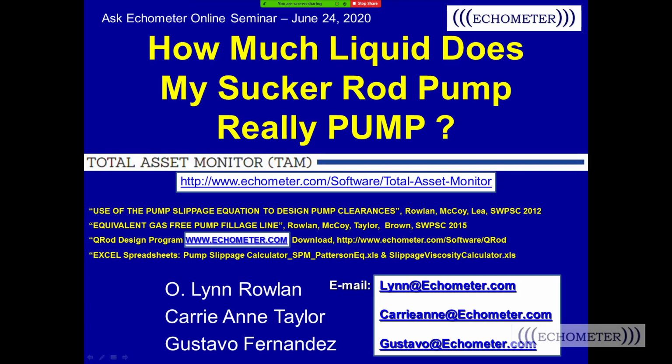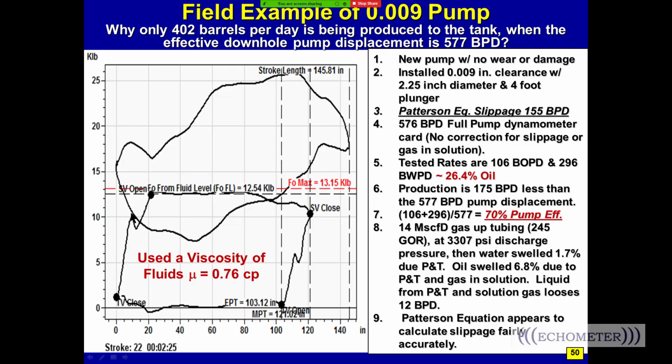Okay, so now you can jump into the last question from Bert. That's yes, slide number 50. You're asking about this little bounce right there and this little bounce right there. When there's quite a bit of clearance, the plunger moves, and then due to the harmonics of the rod string, it pauses. The frequency of this little bounce is due to the frequency of the rod string.